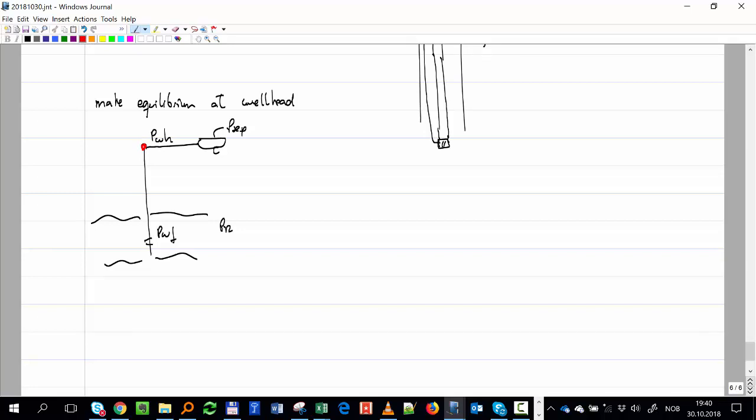How do I do that? We look first at the boundaries, remember, where the pressure is fixed, and then we move from there. We move from reservoir to PWF, co-current, then we move from PWF to wellhead, co-current, and then we stop. And that's the available pressure at the wellhead. That equation we're going to call WPR, wellhead performance relationship.